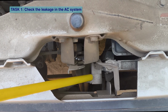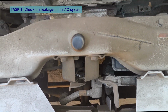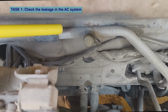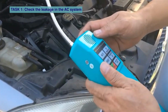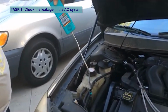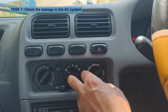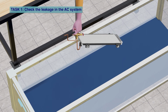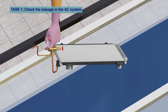Inspect all AC system components such as hoses, connections, condenser, evaporator for visible signs of oil or refrigerant leak. Use an electronic refrigerant leak detector to check for leaks along the hoses, valves and connections. Start the AC system and listen for any hissing sound that may indicate refrigerant leak. Inspect the condenser for any physical damage, blockages or debris that could cause leak.